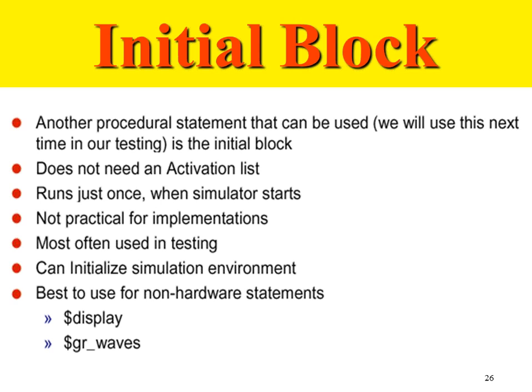Yes, the initial block we use in test benches to initialize the values of the registers and signals. If we do not do the initialization, then the values will be Z or X, so we need to do that in a test bench. But now we are talking about hardware. When you talk about test benches, it is only meant for simulation purposes. Can you apply this concept to hardware?